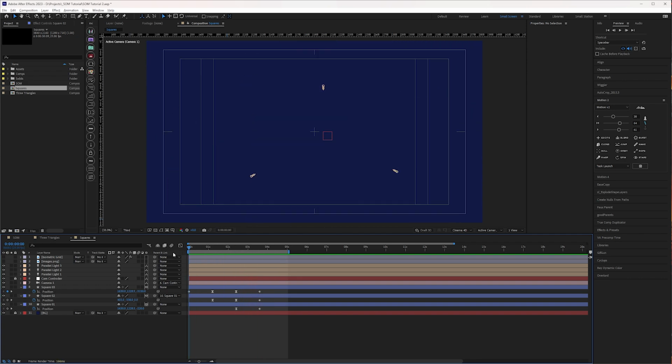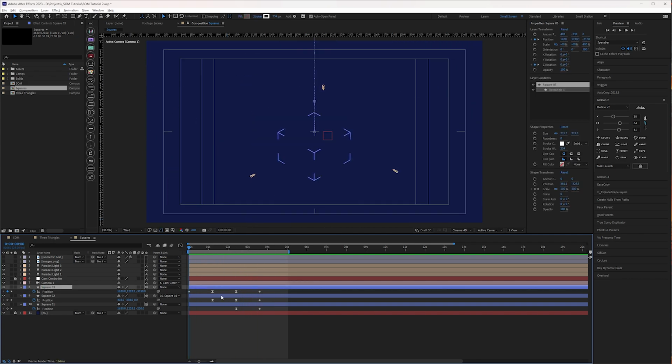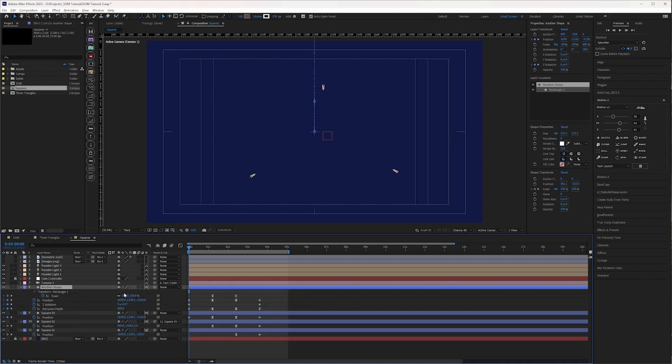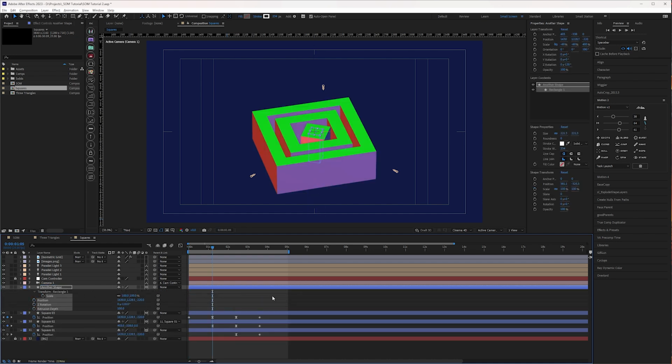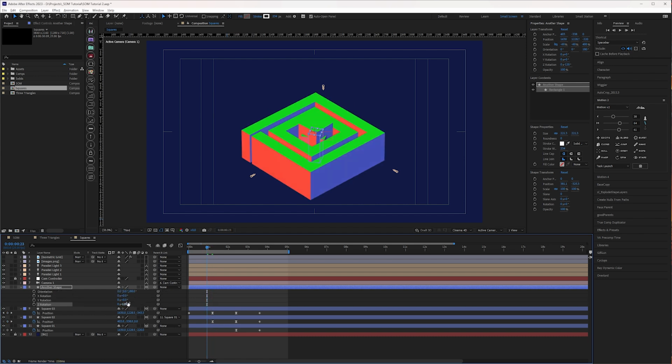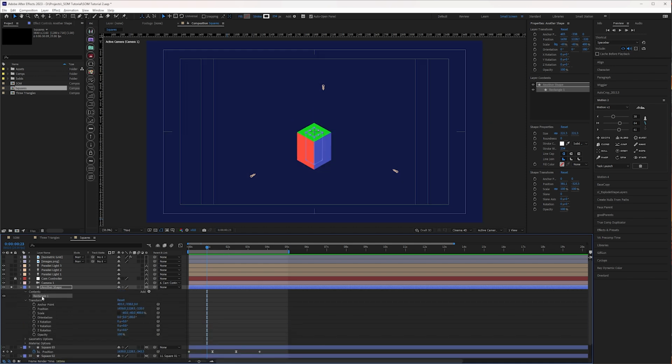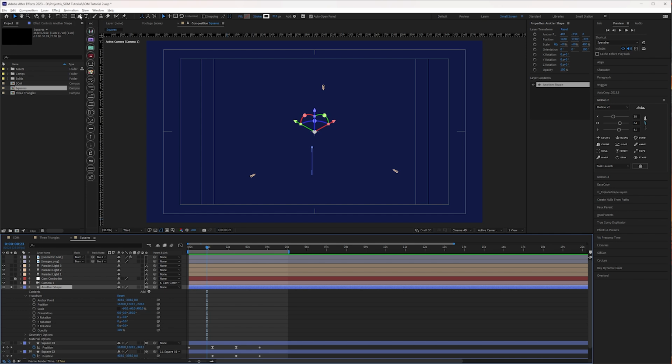What we can also do is try many different shapes. So for example, if we start another duplicate here, let's say another shape, and for this one we will just remove all the keyframes here and adjust the rotation to be 0 and solo this one for now. It's a square, so I'll just delete this rectangle and let's add one of these polygon shapes.